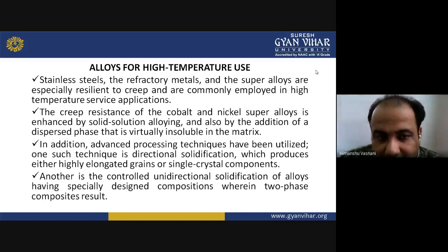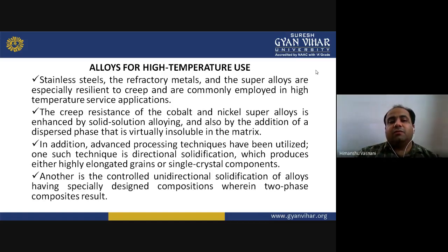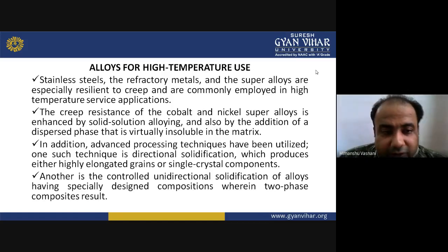The creep resistance of cobalt and nickel superalloys is enhanced by solid solution alloying and also by the addition of a dispersed phase that is virtually insoluble in the matrix. In addition, advanced processing techniques have been utilized.